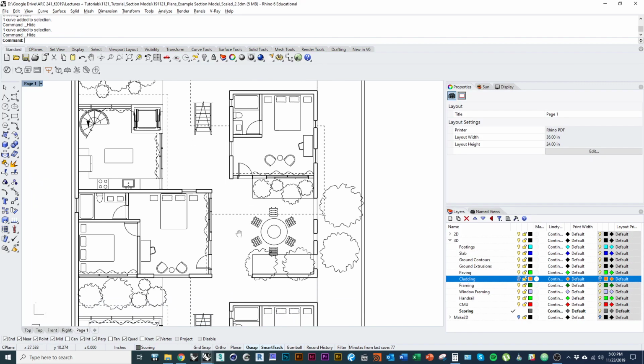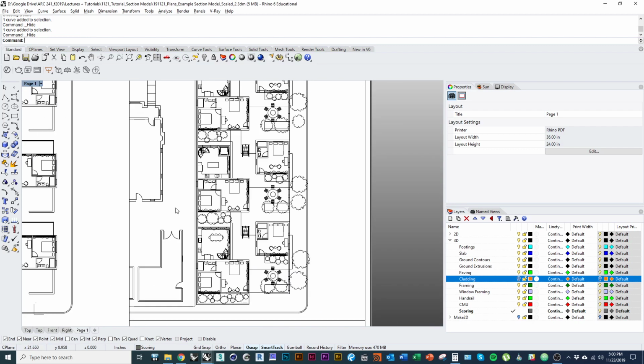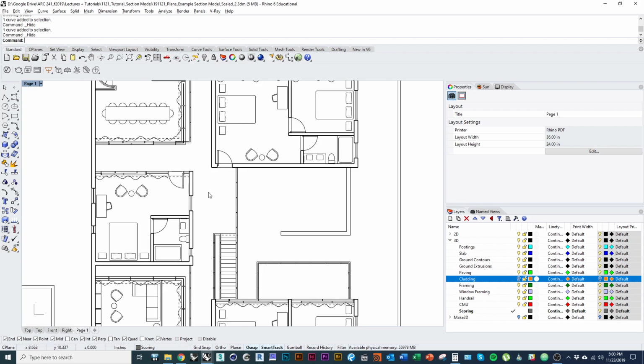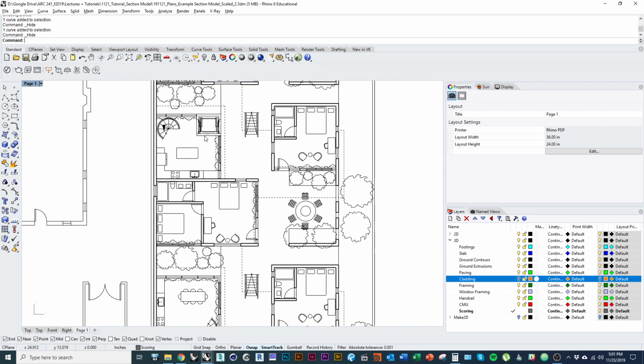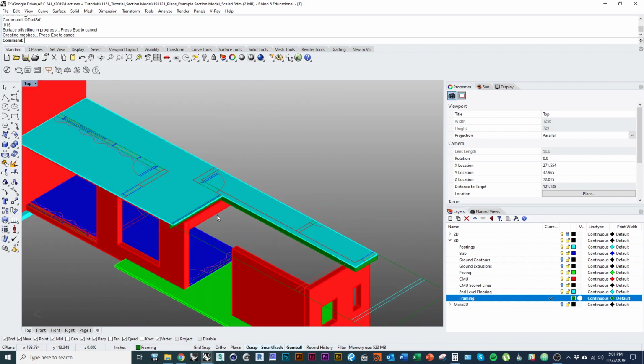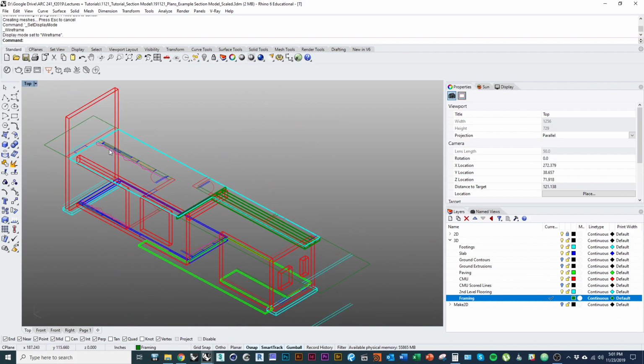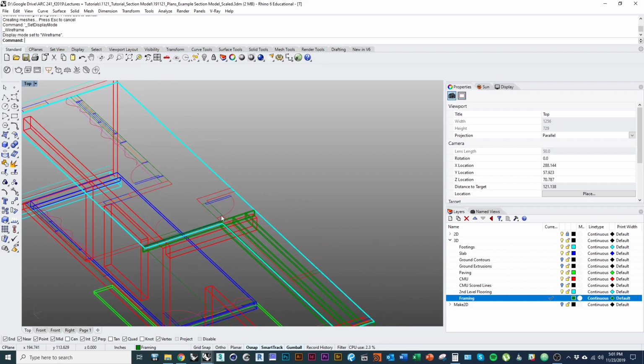And then if we go back to our plan and refer to this unit, and kind of the flooring here, so we're looking at a section of our model in here, and we're seeing the framing come all the way up to that edge. But I think within the floor framing for this, because we're spanning across the major walls in this direction, our wood framing would actually go in the other direction for this part. In other words, we're going to have a bunch of joists that go this way across this part of the floor framing.